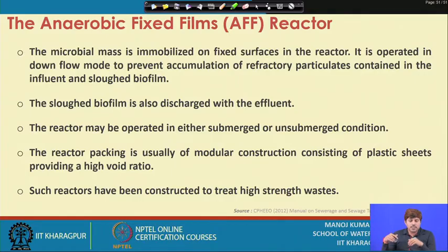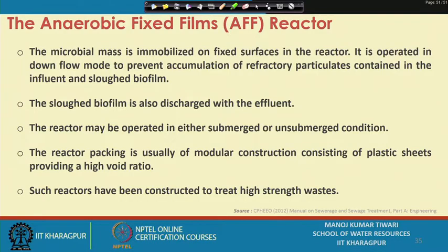Now, these AFF reactors may be operated in either submerged or unsubmerged conditions, and the reactor packing is usually of modular construction consisting of plastic sheets providing a high void ratio. These kinds of reactors are typically used to treat high strength wastewater.